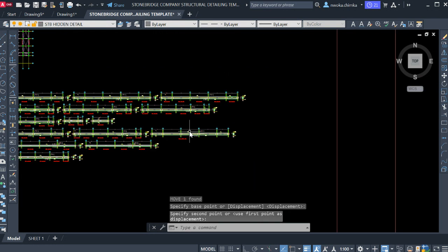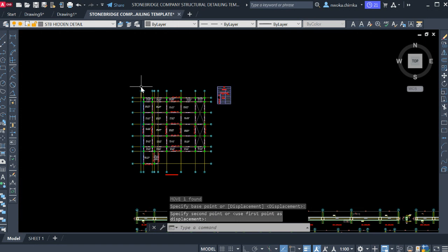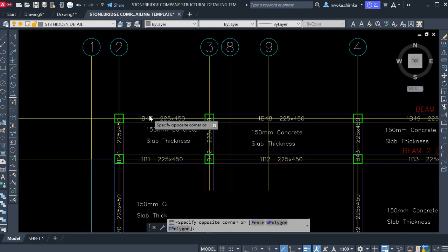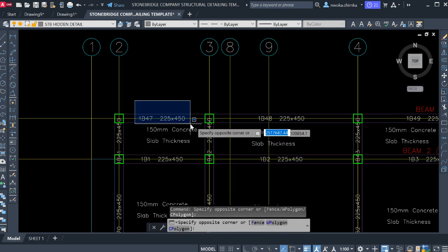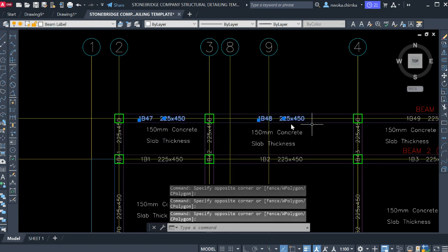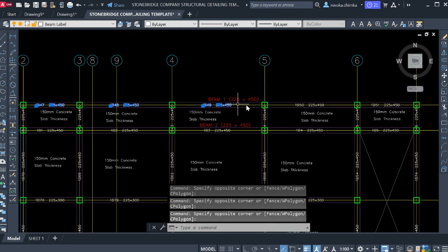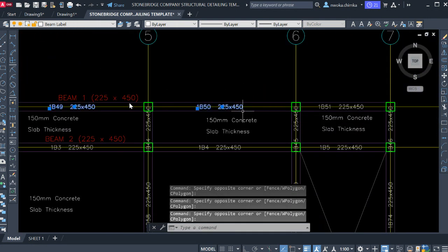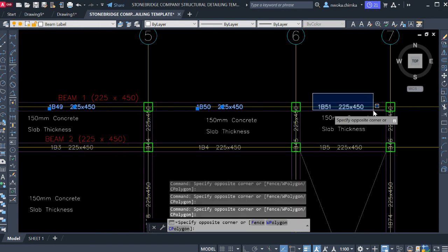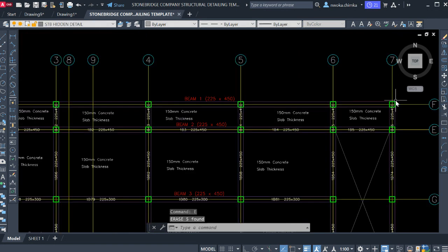The first thing I'll do is remove this, because we have now numbered this beam perfectly. So we remove this beam detail, this beam name, leaving just this one, because this now overrides all other beam names that are on this beam. So we now remove this and delete. So you can see the beauty.